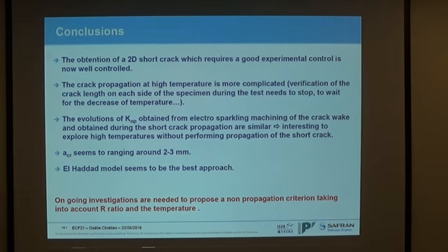So we have to keep in mind that the evolution of crack opening obtained with machining is quite similar to the one obtained with propagation. So it's interesting to keep it for high temperature tests because we'll spend less time to determine the data. We can also say that the critical crack length seems to range around 2 or 3 millimeters, but for the moment we don't know what significance to give to this value. And the LADAM model seems to be the best approach because it is the simplest and because it fits the data well.